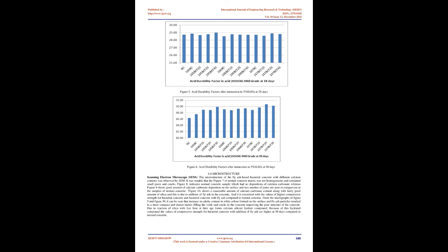The specimens were immersed in 5% H2SO4 and HCl, and readings for weight and compressive strengths were recorded for all mixed types at 7, 28, 56, and 90 days. The solution was replaced at regular intervals to maintain constant concentration throughout the test period.